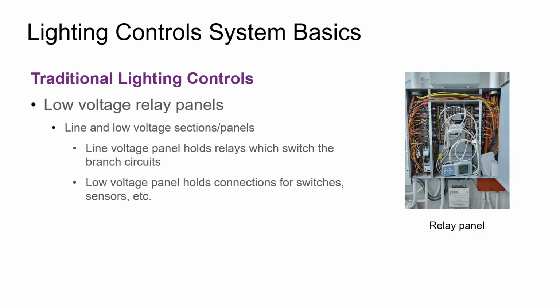You likely have knowledge of low voltage relay panels. These panels consist of relays in a subpanel, which is connected to the main source panel. The relays operate the lighting fixtures based on schedules and occupancy and photo sensors. Schedules allow one to program times when the lighting comes on or off, such as on at 6 a.m., off at 6 p.m., off on weekdays, and so forth.